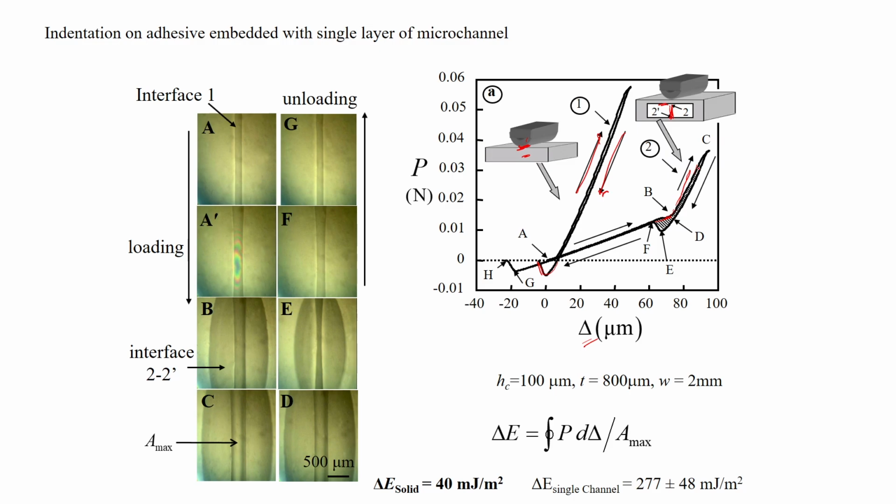When you do the unloading experiment, this curve is not followed smoothly. The load actually decreases, and when it gets separated there is a pulling, and once again this happens and it comes out, like that. So in this region there is a kind of negative modulus that happens. It is a kind of metamaterial effect that comes into the picture, negative modulus over here, and then again it has the slope. That is the effect that we take advantage of, and that leads to enhancement in adhesion. For example, if it is a solid material, then we will have this much amount of adhesion.